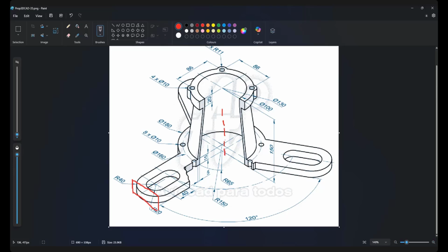Yeah, you are right. 190, then plus the radius of this curve, the radius of the upper one here. This curve is radius 40 here, right? So we have 150 plus 40 is 190, plus 40. 230 or 250? Check again. 230, right? Clear? Yes. 150 plus 40, the length of the slot center is 40, plus the radius of this fillet is 40, right? So 230. All right, so it will be 230.